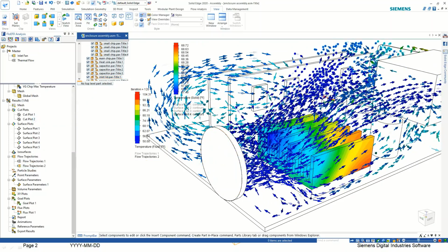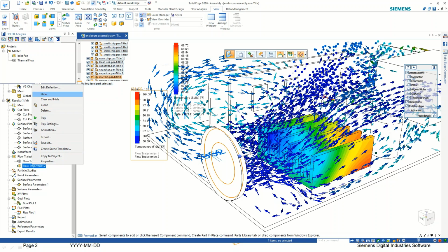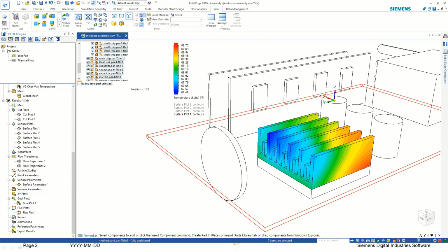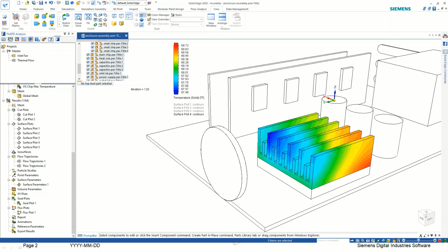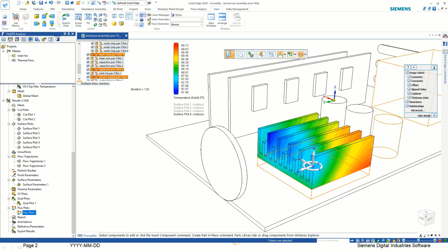and we found out that we have to make the position of the fan in such a way that it reaches the back face of the heatsink also, to make it more uniform. Then we have this option called heat flux plot. So we can select that, and we can go to the option and see what it does.